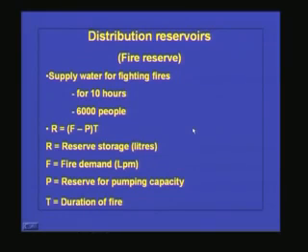Now the distribution reservoirs are also used for storing water for firefighting purposes. Supply of water for firefighting purposes is normally based upon how long the fire is going to last and under what kind of development, how many people are going to be affected by this particular fire. Typically, we consider the amount of water that is required to fight a fire which is going to last for 10 hours in an area where 6,000 people are living.